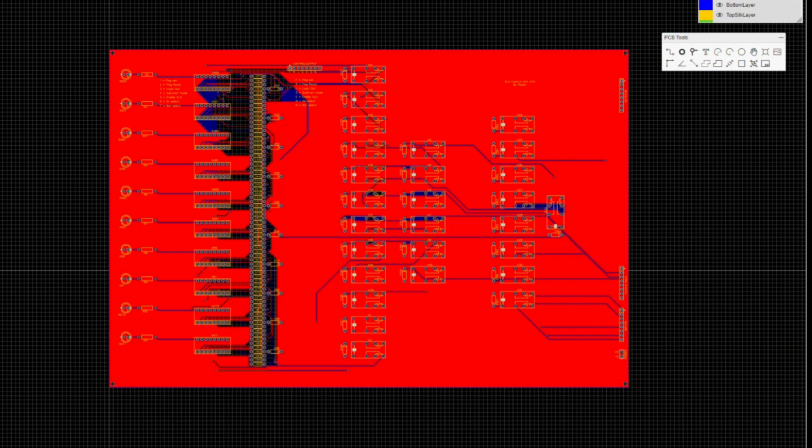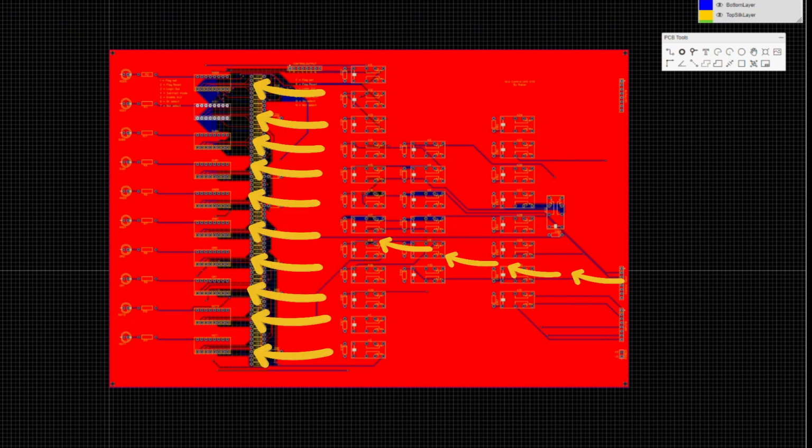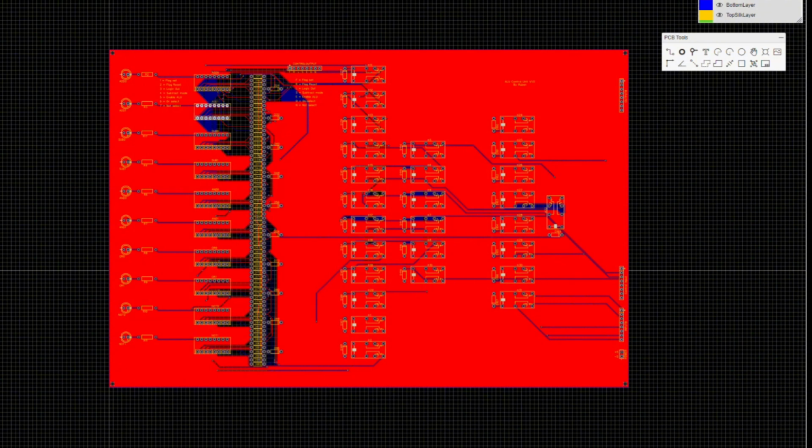Basically this just decodes a 4-bit value into 10 lines, and these 10 lines will then have dip switches, which you can then reprogram to anything you want. So you can quickly change the microcode for the ALU by just changing the dip switches without having to continuously reprint boards, which I think is a much better way of doing it.